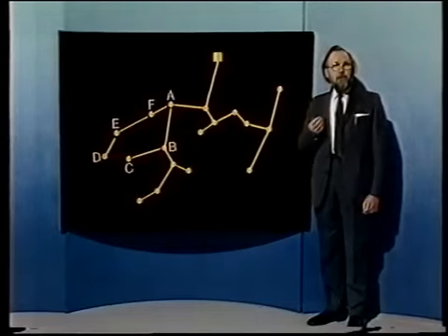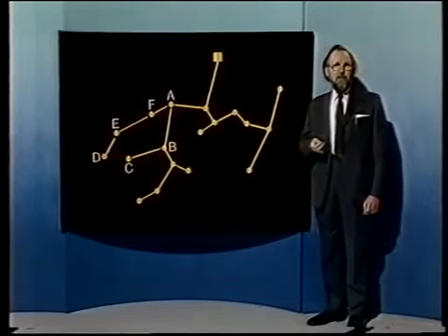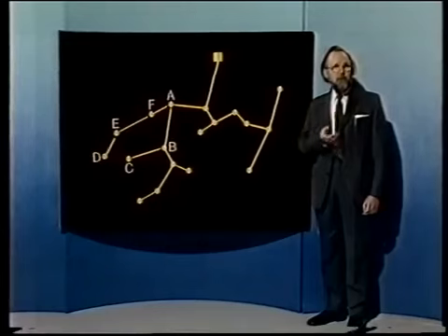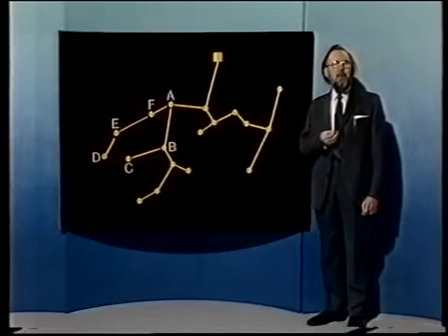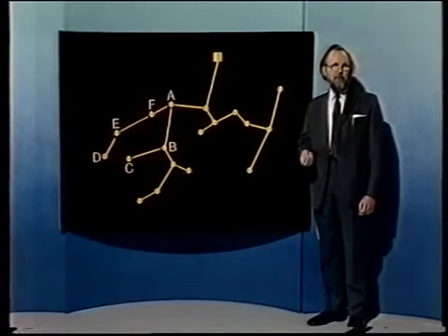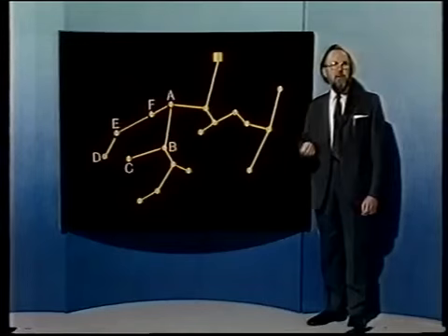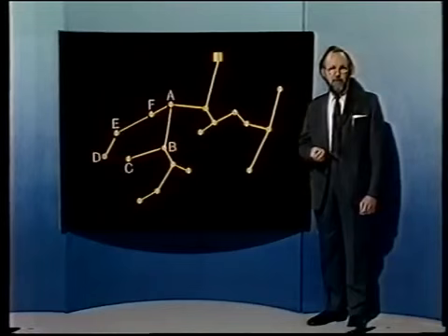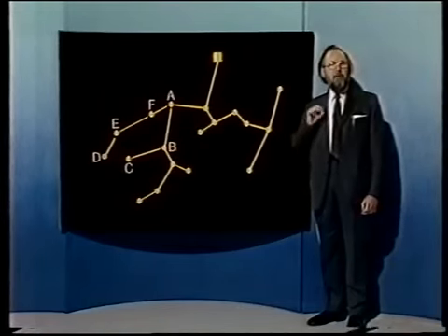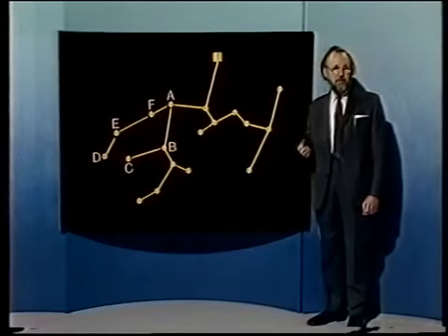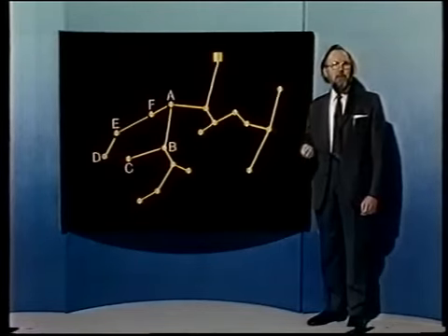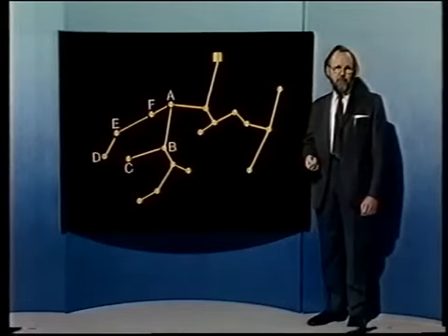Now, if we do this for all the branches of the cycle, we can evaluate the cost of each option and we can choose the cheapest. Now, if in fact we remove the branch DC and apply Dr. Frank's diameter optimizing algorithm to the resulting tree, we find a 20-year cost of $108,912,000. Now, this is a further saving of nearly $200,000. Now, what Dr. Frank goes on to do is to do the same thing for each vertex in turn. And he carries on until he gets a tree which is what he calls a locally optimum tree.